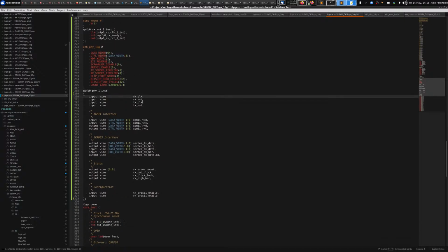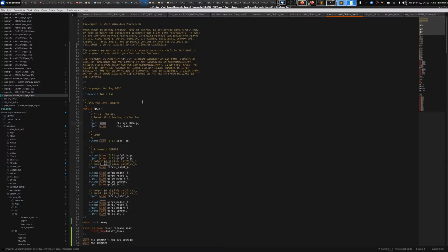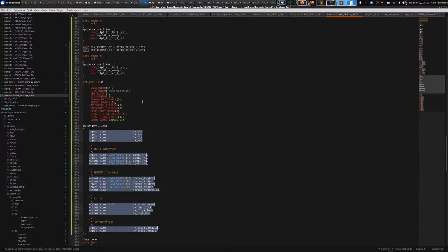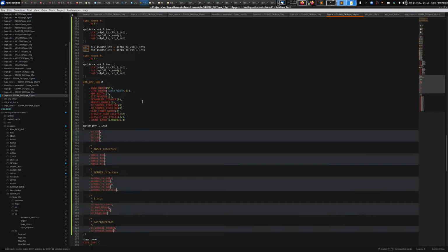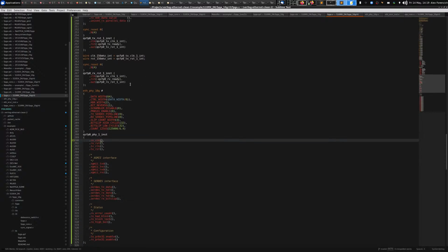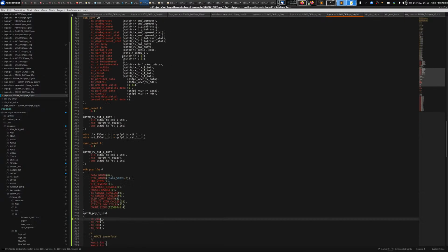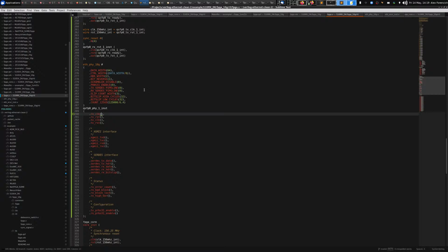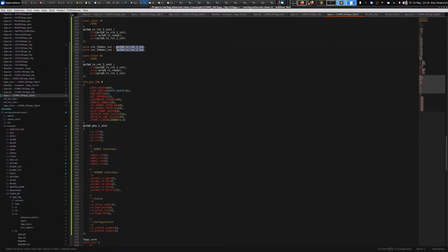Let's go ahead and connect up all of the other signals. All right, all of these wires. All right, so the clock and reset, these are going to come from the TX and RX clocks that were connected before, right? So here are the TX clock and TX reset. So I'll go ahead and copy both and then rename it. I need to adjust my gate. Okay, RX. All right, so there's RX clock, RX reset.